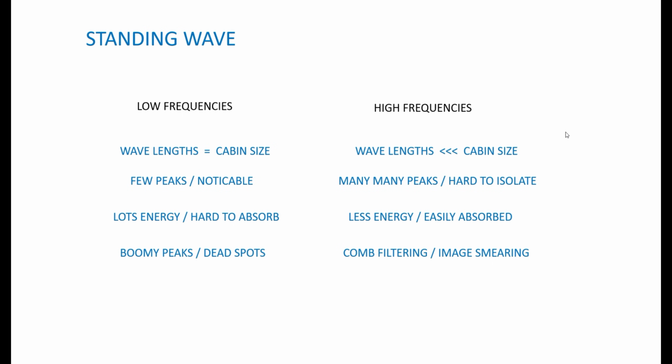Their wavelengths are very, very small, many times smaller than the size of the cabin of the car, and so they're very hard to pick up because there's so many peaks and troughs. The amount of energy from those speakers is much less compared to your subs and mid bass, and so that energy is more easily absorbed by the seats and the carpet and the headliner and things.